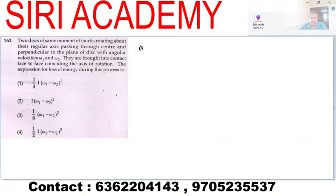So the loss of energy is given by half into I1 I2 by I1 plus I2 into omega 1 minus omega 2 whole square, assuming that both the disks are initially moving in the same direction.